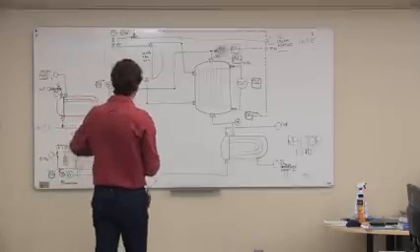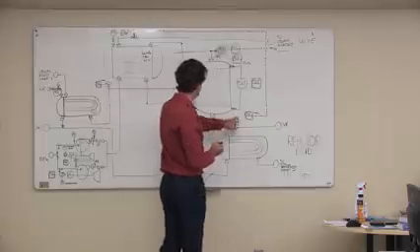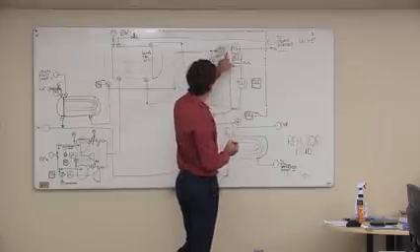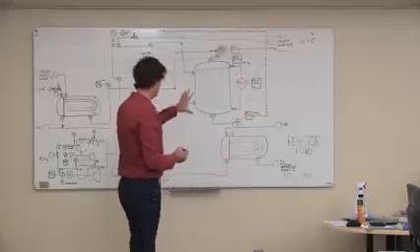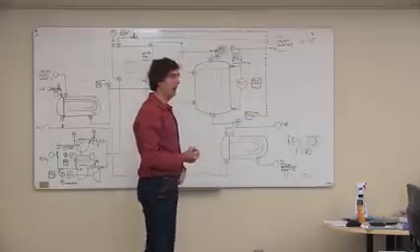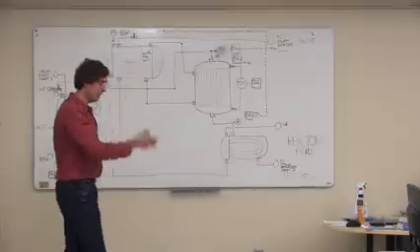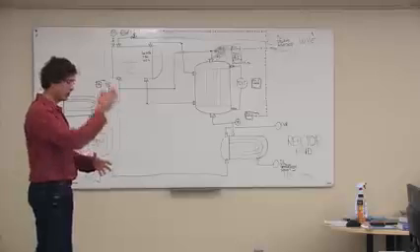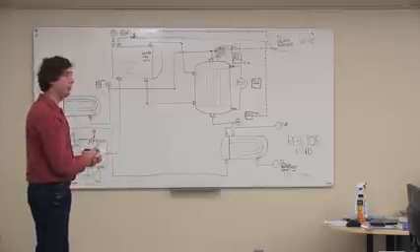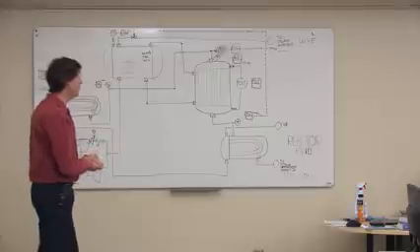We know the inlet temperature, we know the outlet temperature, we know the inlet pressure, and we know the differential pressure across the transmitter. The only thing we don't really know is what the temperatures are actually in the bed. So it'd be nice to know what the radial temperatures are in the tubes. It'd be nice to know what the longitudinal temperatures are down through the reactor. We might want to try and do that.